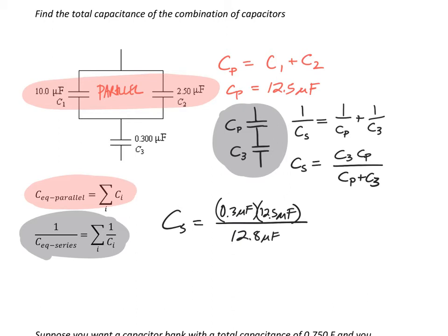So you're going to get one of the microfarad units dropping out, obviously, meaning that it's all numbers times some number of microfarads. Yay. So all of this crunches down to 0.293 microfarad. And I guess if we wanted, we could have 293 nanofarads, whatever floats your boat.